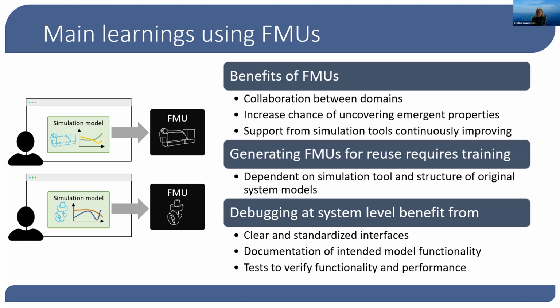You're not supposed to know what's going on inside the FMU, but you should be able to have clear and standardized interfaces and documentation of the intended model functionality. That will simplify this debugging. It would also be preferred to have tests to verify the functionality and performance of a model, that it is according to its intended use, before you start configuring the whole system simulation, because then it can be very difficult to debug when you have everything connected.